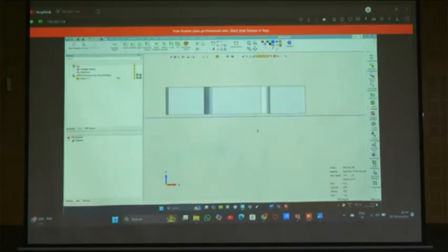And why am I applying some particular height to this? Why do I need to apply the support? I can print it directly, right? That is why. Suppose here I kept it, I have designed with 10 mm, but your tensile usually ASTM E8 standard tensile sample will be 2.5 to 3 mm thickness. Suppose you have designed with 3 mm, you need exactly, powder limitation is there. You need exactly 3 mm output, or 2.5 to 3 mm output. So for that, what we are doing is adding a support in between.